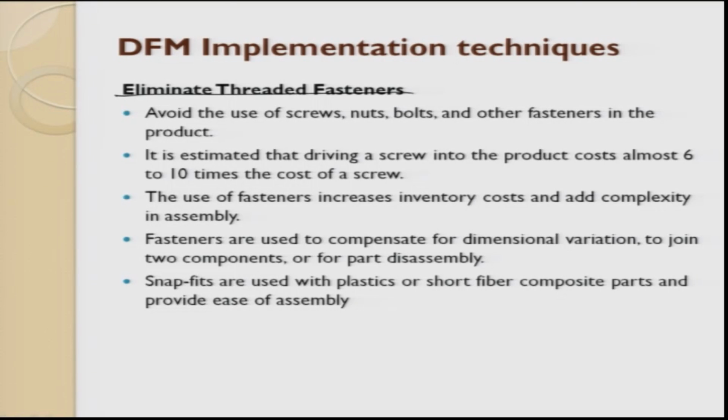Eliminating threaded fasteners. Avoid using screws, bolts, nuts and other fasteners in the product. For example, how do you do it? Suppose you have removed all of them. So what is still left with me? Rivets are left, snap fits are left. So all these things can be thought of, and if you use these, for example the location snap fit.